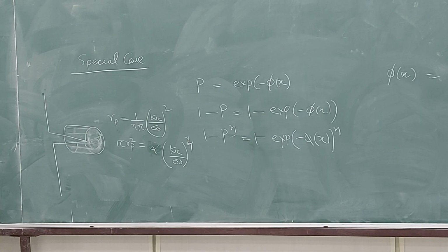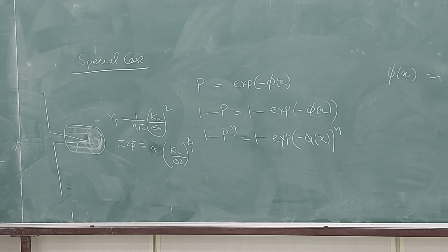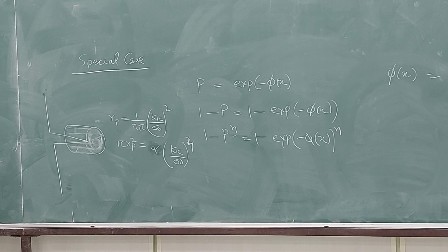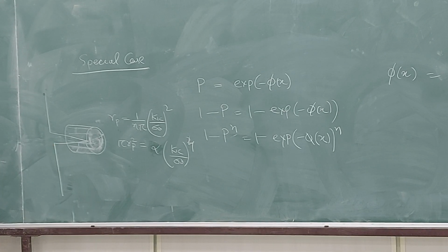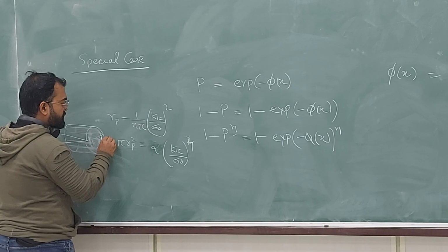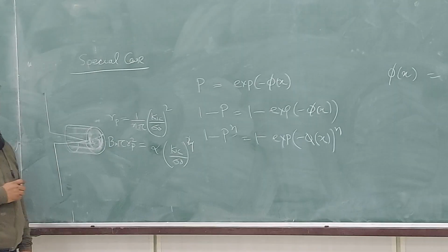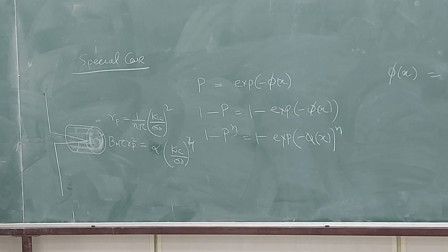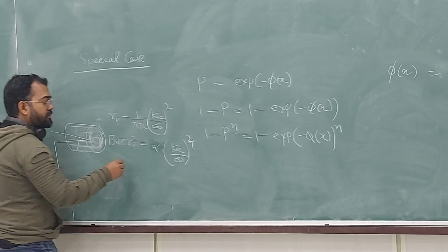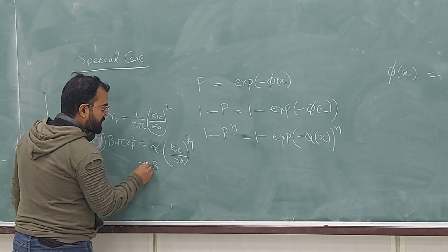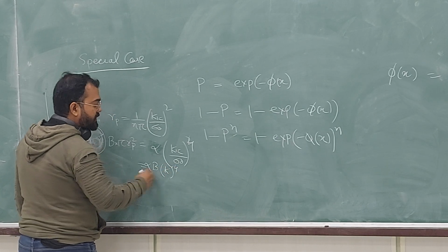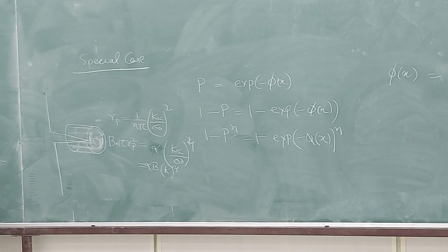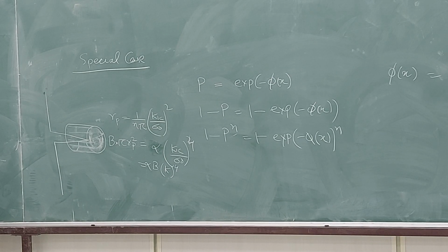Another assumption is that it is plane strain. So I am assuming that the plastic zone is not changing along the thickness. Okay. So I extrude it throughout the thickness. So the volume becomes thickness into area. Cylinder. Okay. So then you have B alpha K to the power 4. Sigma naught will be a constant because that's a material property.